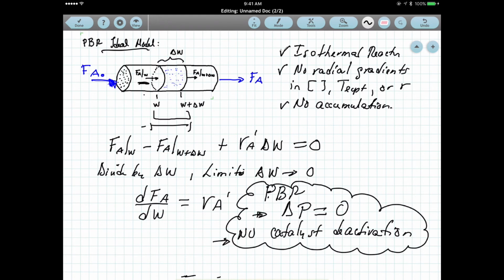So one of the important aspects of a chemical engineer is to actually predict this deactivation, or maybe select a catalyst that lasts long enough to have as much delta P equals 0, right, there's no clogging or fouling of the catalyst, and also that the rate is not changing, because the spaces or the surface area allowed for the reaction are being clogged throughout time.